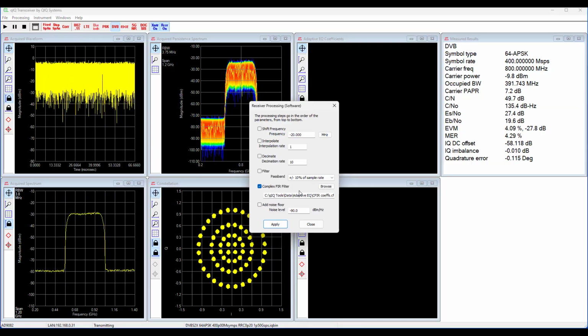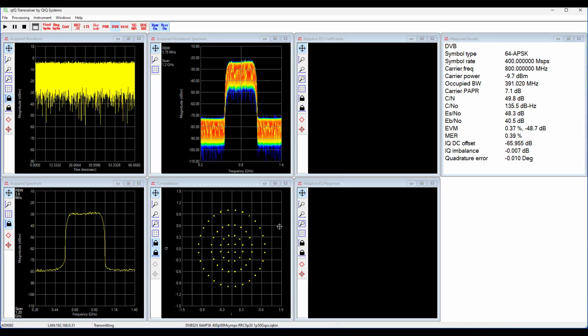So these are the tap coefficients that were generated when we did the 8 PSK waveform at a different symbol rate and different usable bandwidth and everything like that. And as soon as we turn on that, then we're back again to the good EVM case. You can see the final symbol constellation points here, and I'll stop it. And so carrier to noise is about 49.3 dB. The final EVM is minus 49.1. So again, we're very close to the theoretical signal to noise ratio that we would expect.